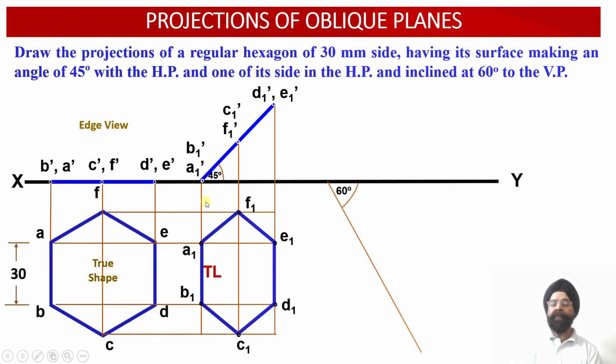Now how do we transfer this figure onto this 60 degree inclined orientation? We have inscribed this hexagonal apparent shape into this rectangular figure over here. So what we are going to do? We are going to measure the shorter length of the rectangle. We are going to measure the longer length of the rectangle. We can check the longer length of the rectangle we have placed over here alongside 60 degree, and over here A2 and B2 points will be located, and this is the shorter edge of the rectangle.